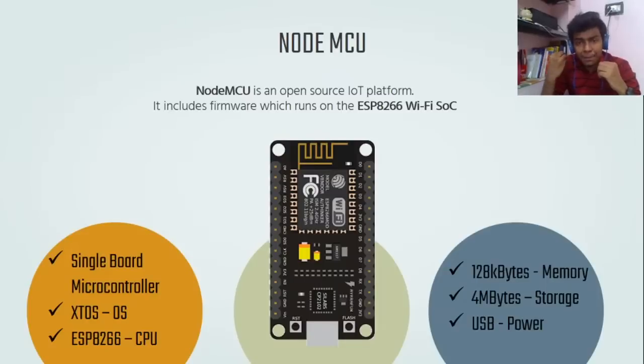8051, ARM or PIC, there we require two applications. One is a compiler, called the Keil compiler, which is required to convert your user language to machine language. You write the code in embedded C, and the Keil software converts the C program into a .hex file. Then we use another application such as FlashMagic for NXP Philips ICs, or SST for SST based microcontroller ICs.